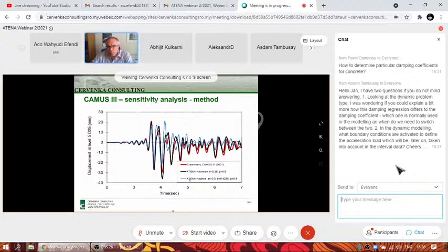And it is interesting to see what happens if we use this alpha method. If we activate this use alpha method, which you can think about as adding some additional numerical damping, you can see that this method works quite well in these first cycles, but then we start to have some deviation from the correct solution.